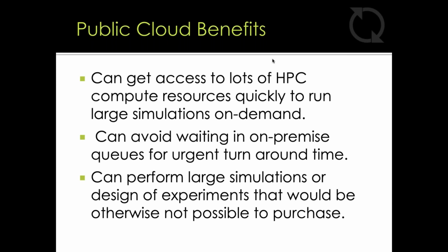It also allows you, if you have a cluster on-prem, to avoid waiting in queues. So if you have a lot of workload and maybe you're a supplier that has to get a result back to the OEM by morning, you can now skip ahead and run that on cloud and get that answer back in time to meet your simulation deadline. Another popular use case is running large simulation DOEs, where you run thousands of iterations to find the best design using some type of design of experiments tool, and you can run those on cloud to optimize your design.